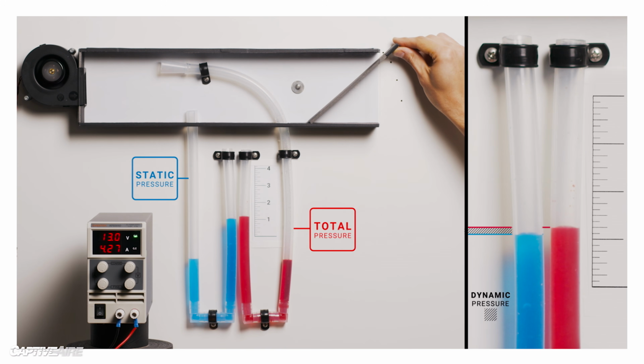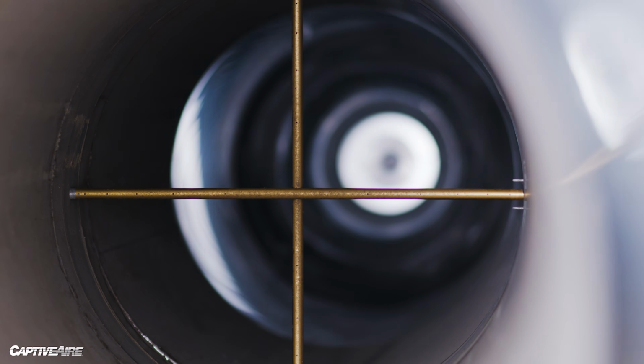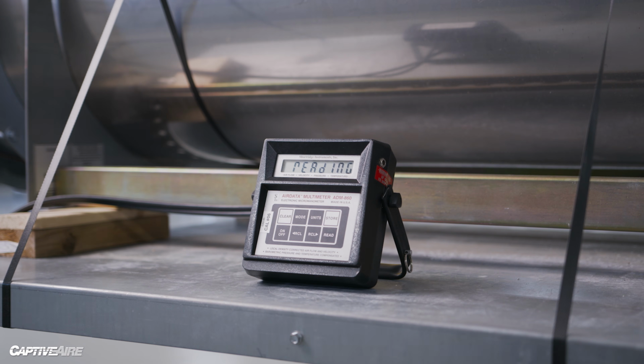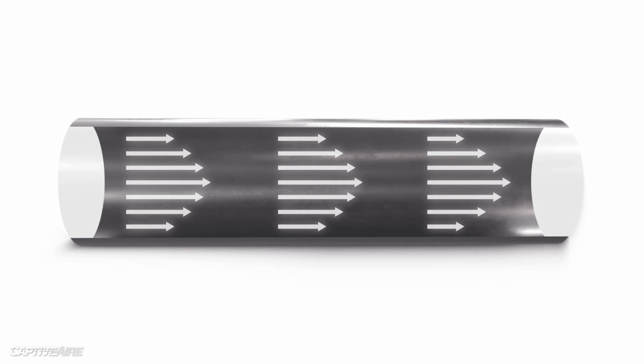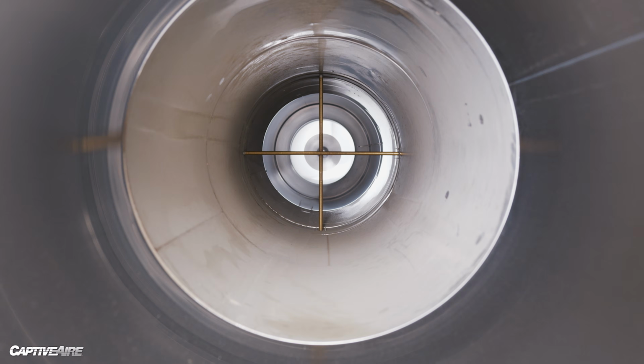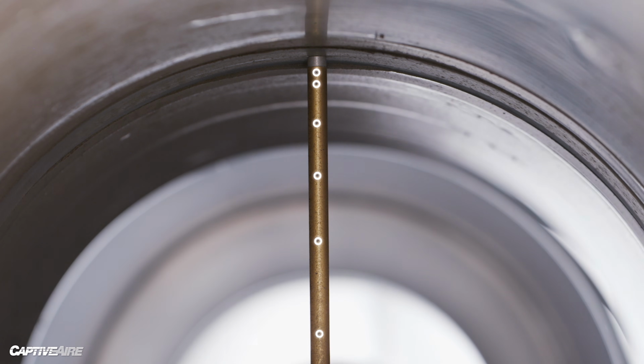In the previous video, we looked at this difference in dynamic and static pressure and how it can be used to calculate airflow. And this setup does exactly the same, but it has to be much more accurate. For example, air doesn't flow at the same rate within a duct. It actually travels faster through the middle. So rather than picking up one single dynamic pressure point, this setup uses several to account for these differences.